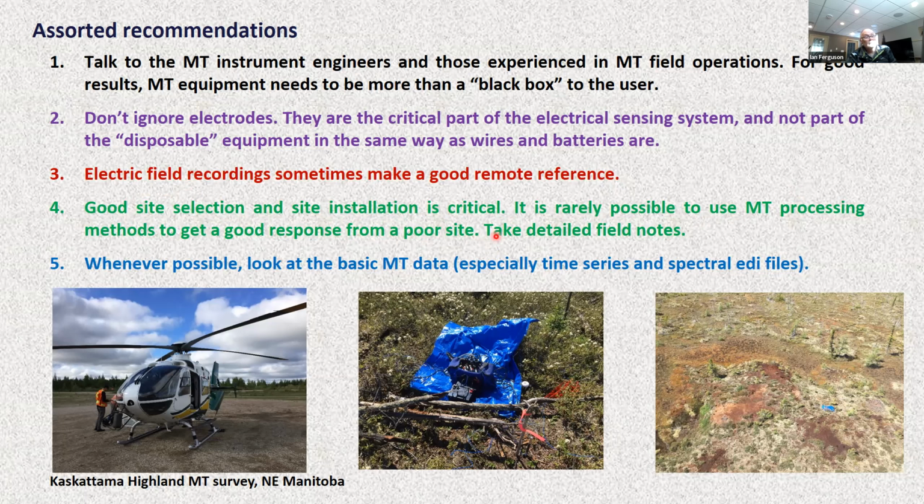Likewise, take really detailed, copious field notes. It's often hard to extract the information from your own brains when you get back from the field. Make sure everything's written down. And finally, wherever possible, to fully understand the MT data, look at the MT results, look at the data. If you can, have a quick look at sample time series from a survey. If you have spectral EDI files, look at spectra, signal to noise ratios, and so on to try and get an understanding for the signal and the noise levels in the survey area.